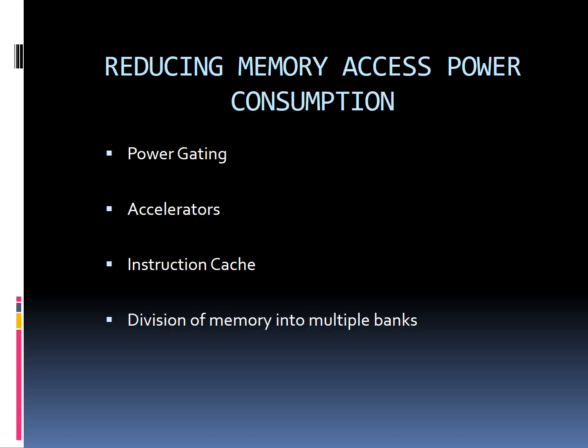Although microprocessors have small on-chip memories, since instruction fetching occurs frequently, an optimal cache configuration can be set up to speed up the fetching. Since the on-chip memories are already small, the caches must be designed to be of even lesser energy access than that of the on-chip memory so that some energy saving can be done. If the caches are of larger size, the hit rate might be high, but the cache access energy will surpass even the memory access energy, thereby defeating the purpose of caches.